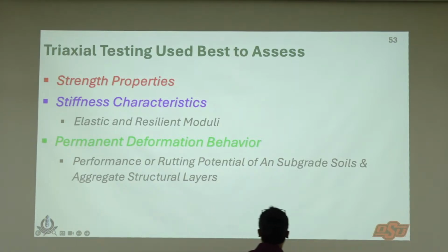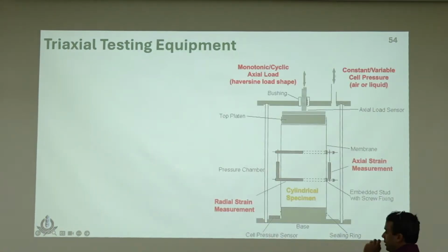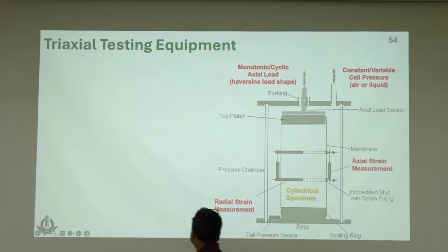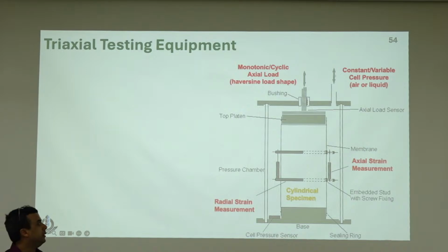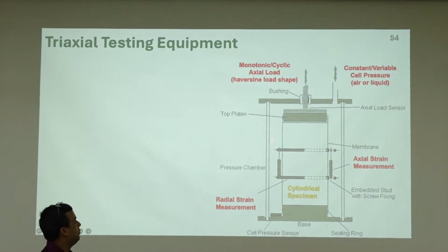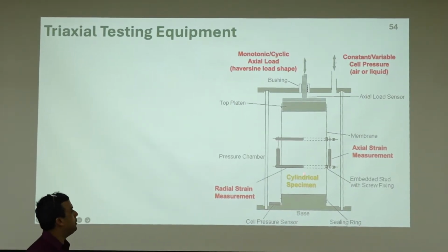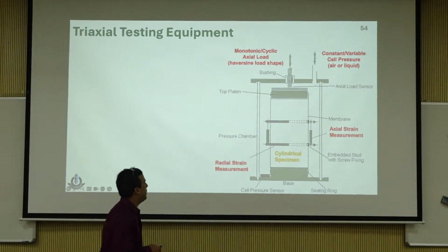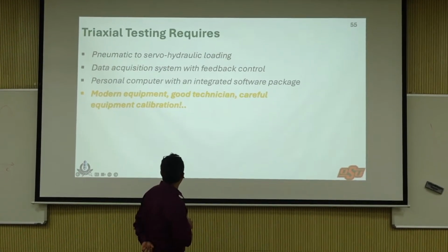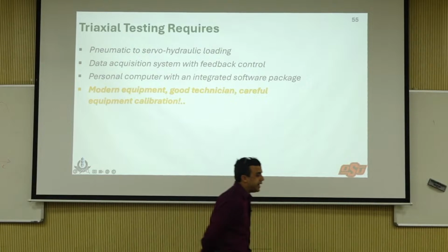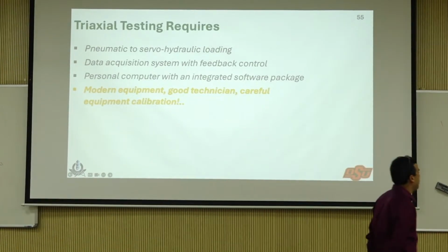Still have a lot to cover. So we are in triaxial testing still, just basic components here. The whole system is in a chamber, and that's what applies the pressures. The loading can be either pneumatic or servo hydraulic.